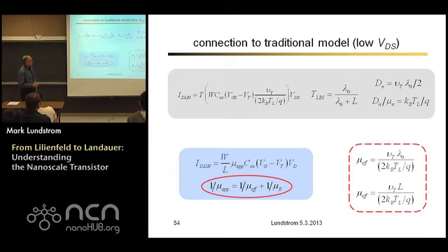And what is that ballistic mobility? Well, when you lump all of these parameters together, it's not surprising that the mobility depends on the average distance between scattering events. All right, that makes physical sense. The more scattering, the less that distance is, the smaller the mobility is. That makes perfect sense. That's a real mobility.